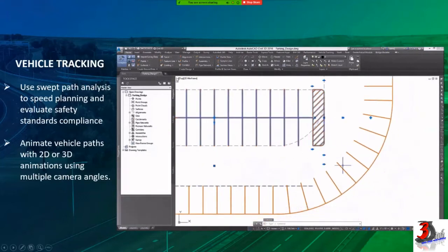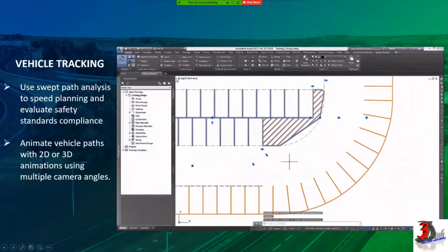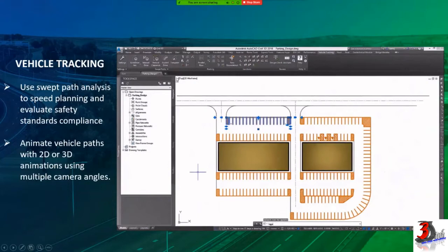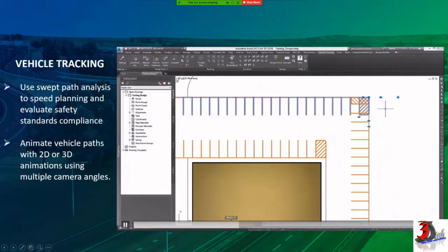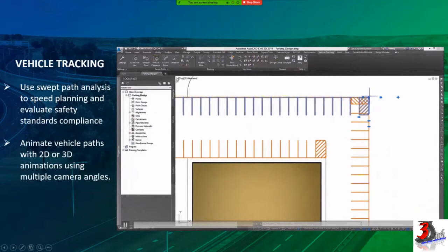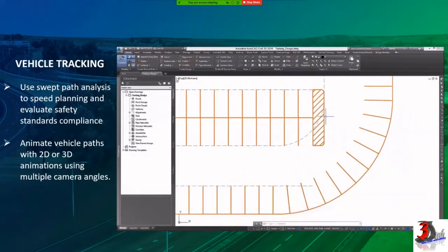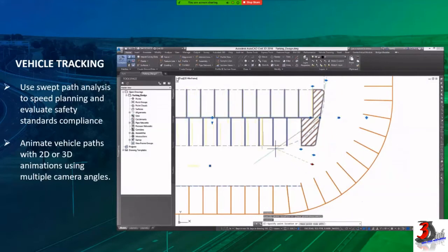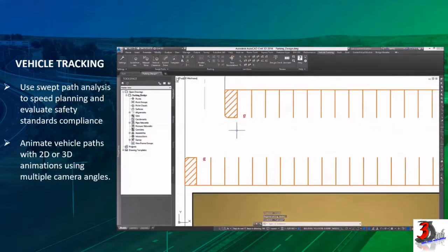And when you place a parking row, Autodesk Vehicle Tracking will limit how close you can put the parking row to another, to maintain the minimum driveway according to the project standards. So this is the minimum driveway for the project standards. We can leverage the parking row intelligent grid to modify the island so it does not approach the driveway. We can also run a quick parking report indicating the number of parking and handicap parking.